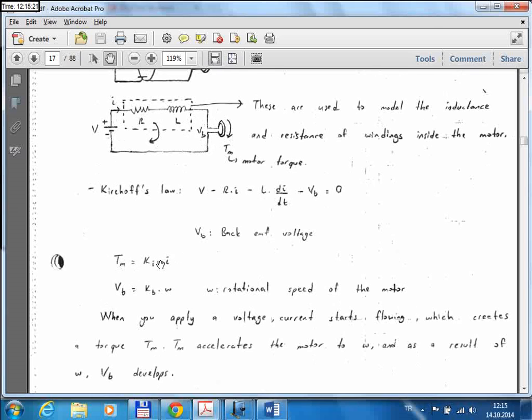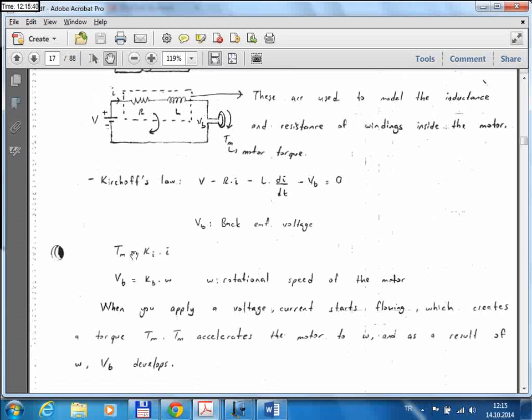Okay, so these are all linear equations if you look at them. So we have current here, and it's just a current by itself, so there's no nonlinear function, and there are no cross multiplied terms like current multiplied with the angular speed or any other such nonlinearities appearing in these equations. So as long as all these numbers are constant numbers, everything is linear in this set of equations. So with these assumptions, the motor becomes a linear system.